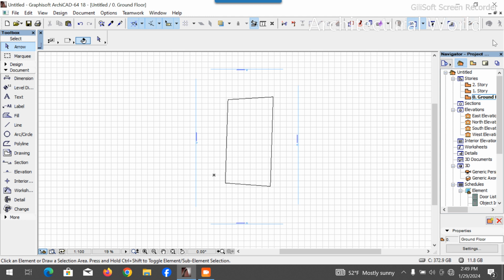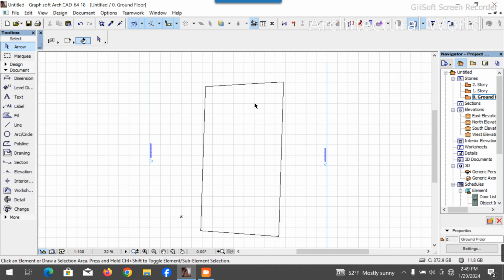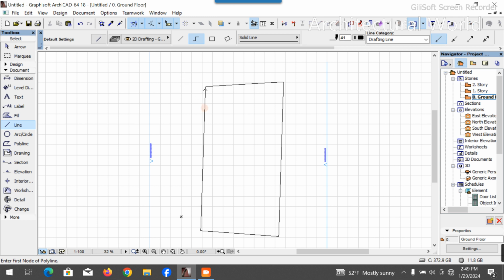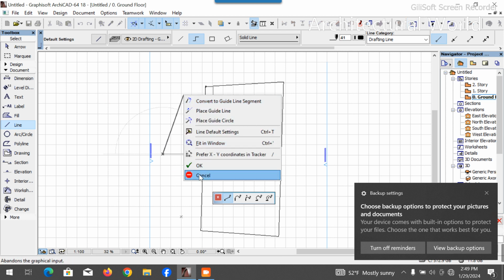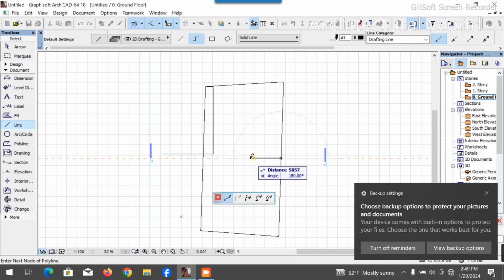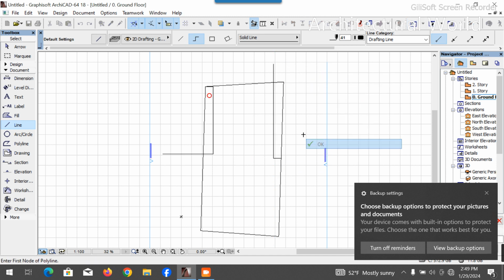Okay. So first of all, this is my land. I always tell you guys, approval standard for all building is 1.5 or 2 meter. So first thing I'm going to do right now, I'm going to take away 1.5 meter from this. Okay, fair enough. Then let me try this side, 1.5 meter. Okay, fair enough. Then let's take this back to be 2 meter in case of septic tank. Let's take 2 meter from this side.